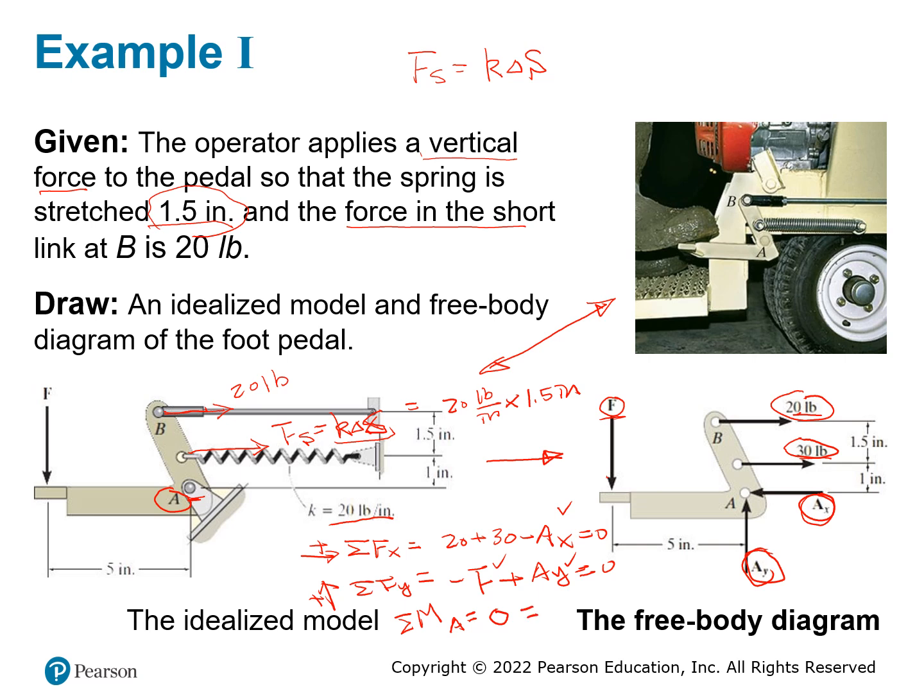And what is the moment around A generated by the forces on this device? We still have 3 forces. So this F here is going to create a counterclockwise moment, so it's positive. What is the lever arm of this force to A? It's not this distance. It's this distance. Okay, this is the distance you're looking at. So this distance is 5 inches.